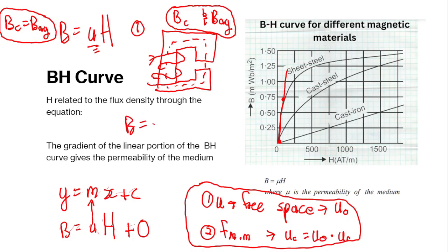B is equal to mu H. If you change the material, you're changing mu, because the material will have a different permeability. But since B is the same, you'll be able to calculate the H from it. So the B will be the same. Makes sense. I thought it would change. So if they give you a global B, you can do everything with that. You don't have to do anything separately. So you good there, right? Nice. And we continue.